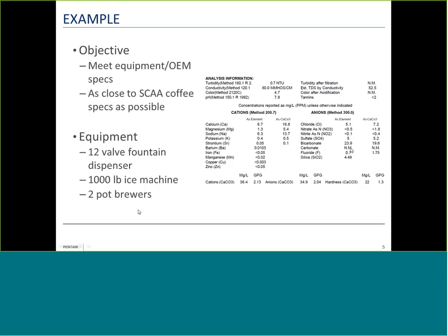But as we get close to boiling, which is 100 degrees C or 212 degrees Fahrenheit, we notice that the tolerance for chloride for stainless steel to prevent corrosion drops to 0 somewhere around 85 degrees C or around 180 degrees Fahrenheit. So there's going to be corrosion if there's chloride in the water at boiling or near boiling.